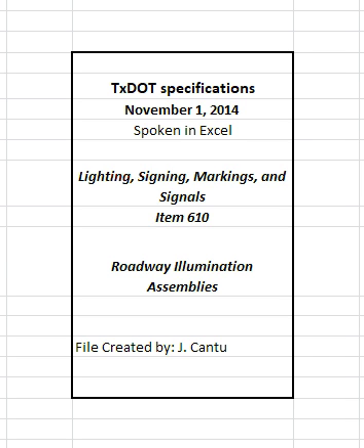Test installed roadway illumination assemblies in accordance with Item 616, Performance Testing of Lighting Systems. Disconnect and remove conductors from abandoned circuits. Remove abandoned conduit or ducts to a point 6 inches below final grade. Reconnect conduit and ducts to be reused. Replace damaged conduit and ducts.